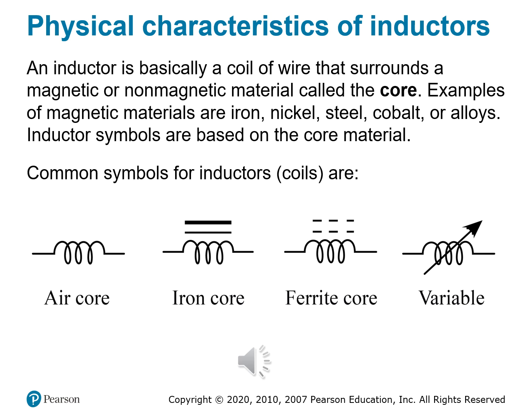An inductor is, at its most basic, a coil of wire, but what's inside that coil, its core, matters a lot. So the core is the material around which the coil is wound, and it can be air or just empty space, a magnetic material like iron, ferrite, or steel, or even an adjustable mechanism, as in variable inductors. And the purpose of that core? To guide and concentrate the magnetic field, which increases the inductance.